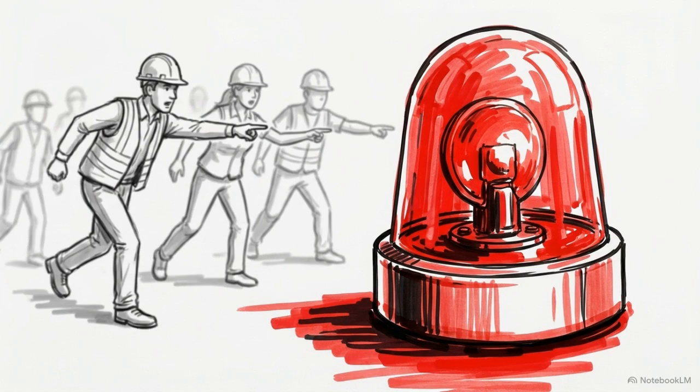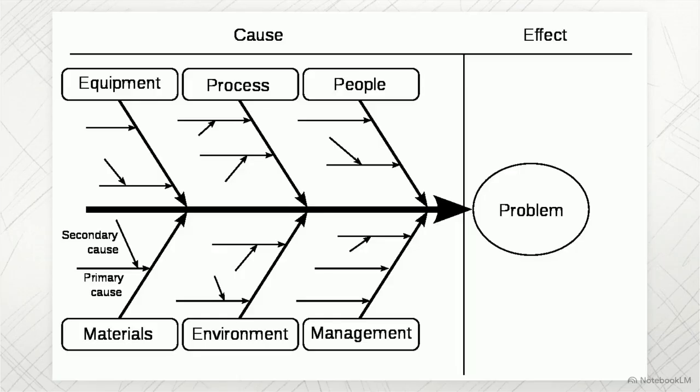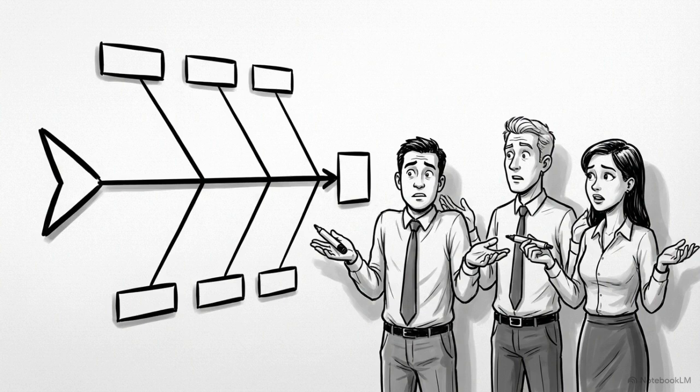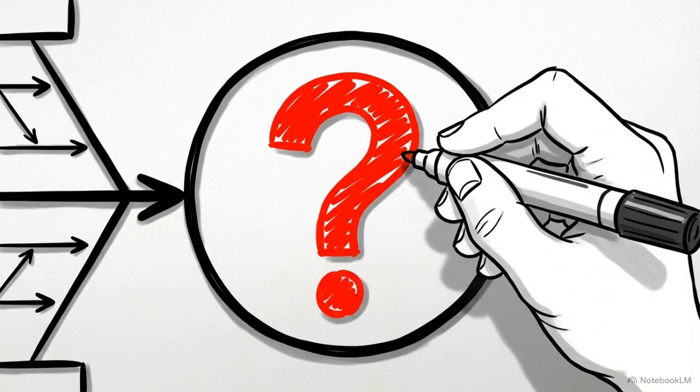of diagnosing the defect. This is the Ishikawa, or fishbone diagram. It's a qualitative, reactive tool used to brainstorm root causes after an adverse event occurs. It organizes human insights by mapping subcauses into primary categories, known as the 6 M's: machinery, methods, materials, measurement, manpower, and Mother Nature. The operational trade-off of the fishbone is its subjectivity. It relies entirely on the prior knowledge and opinions of the personnel in the room. If the team lacks experience, the diagram will not uncover the true root cause.